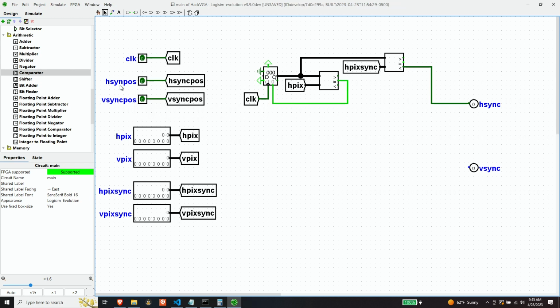But remember, I had this bit here that is trying to define whether we want a positive going horizontal sync pulse or not. And so it's, of course, not quite that simple. There's several ways to do this probably. My programmer brain tells me to just put a mux in here, muxing on this bit value, and either invert this signal or not. Let's just do that.